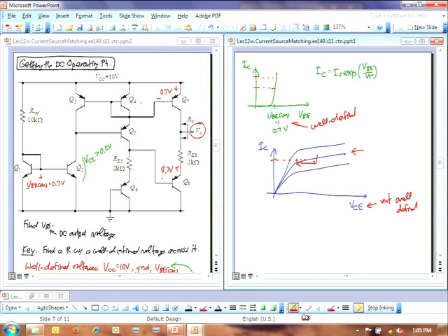Yes? So all the math that we've done for BJT is largely in the forward active region. We have to assume that any of these was a saturation. How do we get the current for that? We just look at the graph and see. No, if it was in saturation, then I would just make the voltage VCE of Q2 0.2 volts. I would make the voltage VBE 0.8 volts, and then I would just solve everything that way.